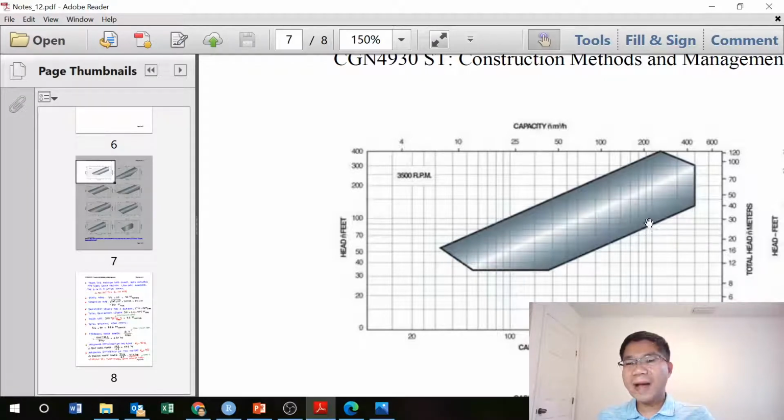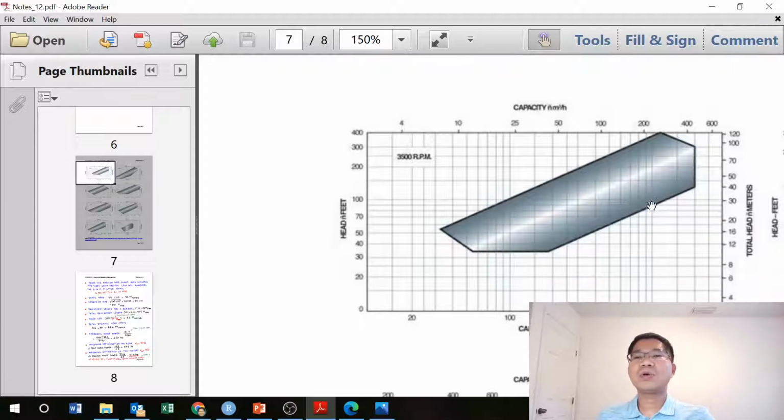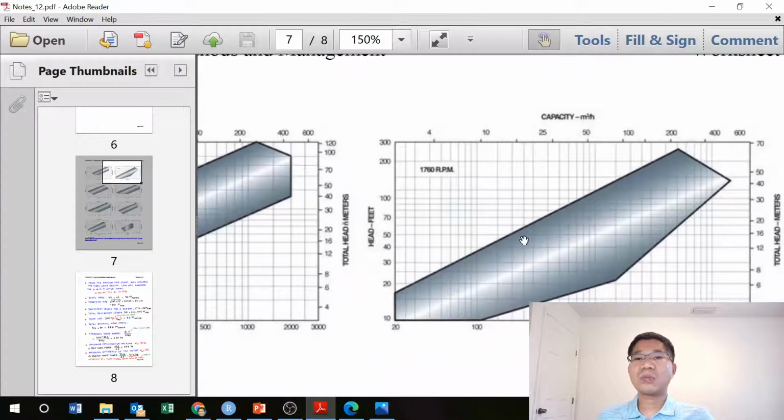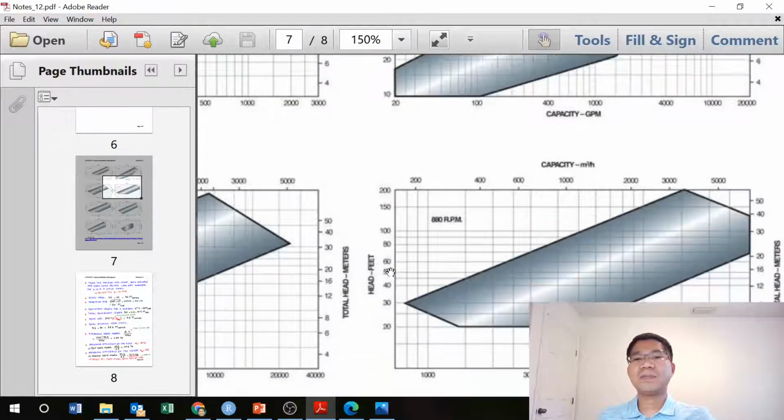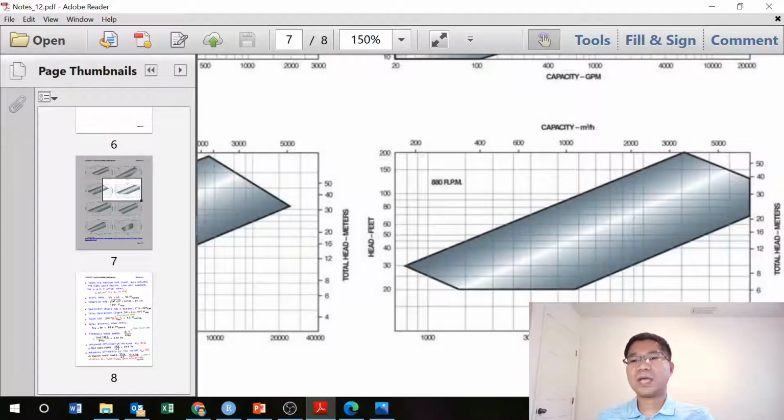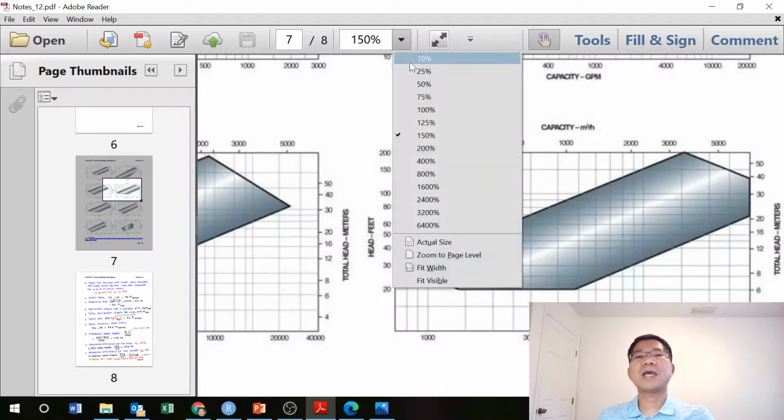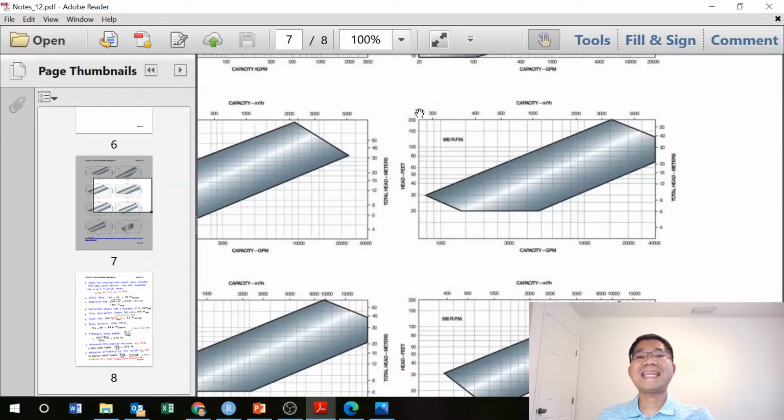So it's about to get into the efficiency zone, but it may not be a good idea. But if you go to the one that we select, 1200 here, it goes to the efficient zone, and similarly other models can be matched well. For example, this one, A80, we can have 12, go to A80, it's in the selecting zone, so we can select a different pump that meets the needs of our problem, not only